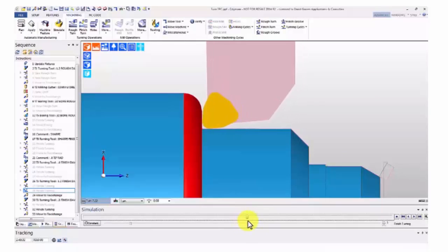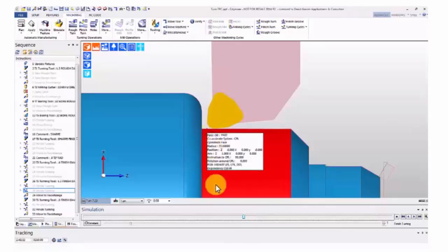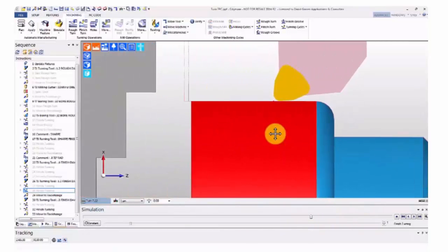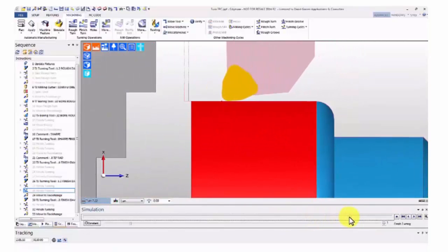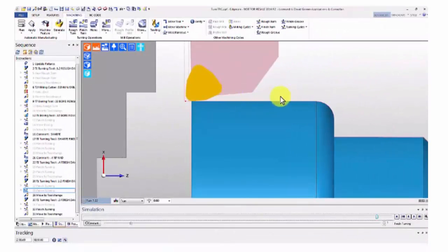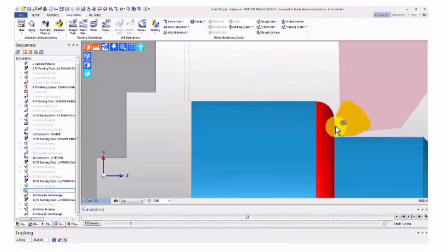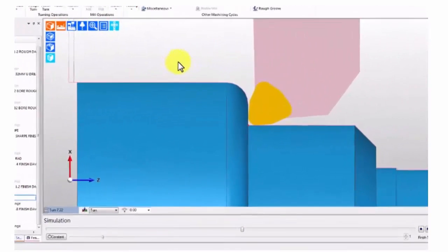So when it gets to the end of that line, we don't want it to go all the way over to this point here. We want it to actually stop there. So it's got to know that the line afterwards is actually a vertical line upwards. It's not carrying on. Just the same as when we get to the end of the shape. If you watch this at the end of the shape, we don't want it to finish there. We actually want it to finish there. So when it sees the G40, when it's coming along this line, it says, oh, the next line's a G40 cancelling the comp. I need to finish this shape off. Whereas when it's coming up this one, it doesn't. It comes to there because it's getting itself ready to go up there. So it's got to be able to look ahead.